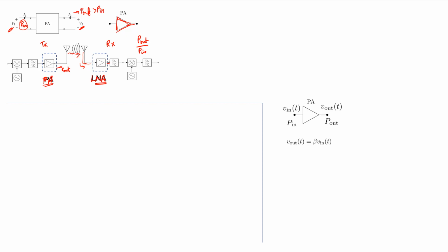In a typical communication system, let's say some kind of Bluetooth link, there could be a transmitter with a certain transmitted power, and a receiver at a certain distance. Depending on the distance of the receiver, the signal received can be very low in value. For example, in the Bluetooth protocol, it is necessary that the receiver has a sensitivity of minus 60 dBm. That means it should be able to receive any Bluetooth signal all the way down to minus 60 dBm, and the transmitted power is typically 0 dBm.